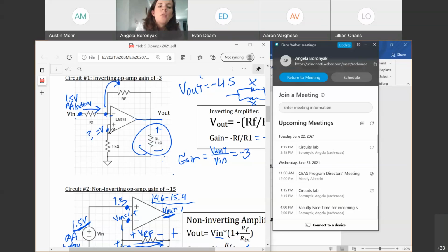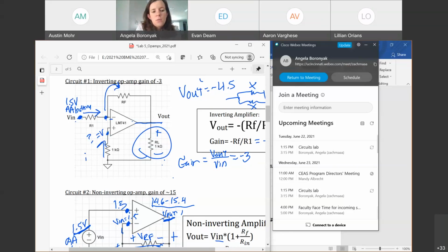What voltage will I be? Will I have current through this resistor, this 1 kilo ohm resistor? Yeah, I'm going to have no current through it, so 0 amps, which means it also has a 0 volt drop, delta V. And it started at ground, so if it dropped no voltage, my voltage here will be 0 volts.